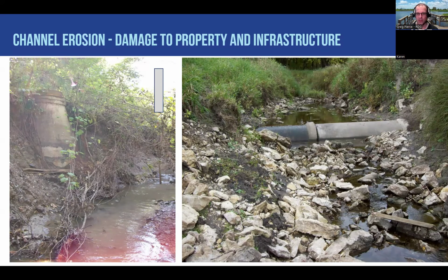Infrastructure that's imperiled. We see here a trunk sewer that's exposed by some of the erosion, and a sanitary manhole here. And this is an area where later on, about 2-3 years after this photo was taken, we had a series of 3, 4, 5 inch rainfall events that happened 3 consecutive nights. It ended up washing out the sewer. That basically flipped one of these manholes on its side, exposed the sewer to the creek, and then there was an emergency repair that had to be done.